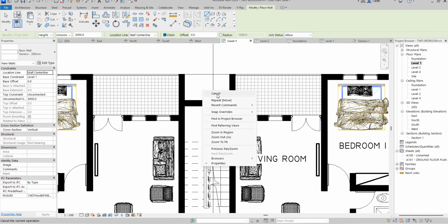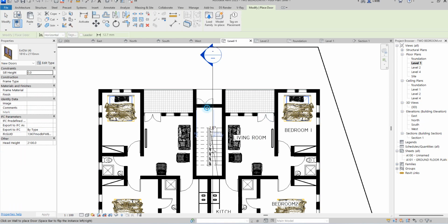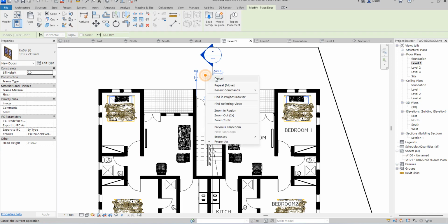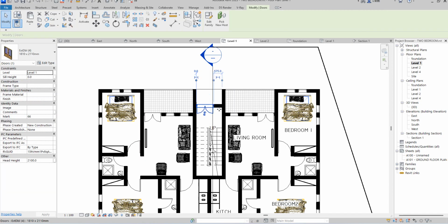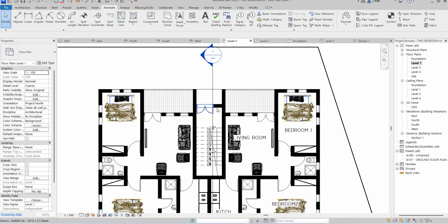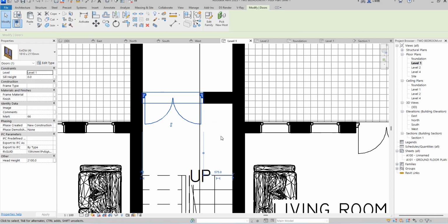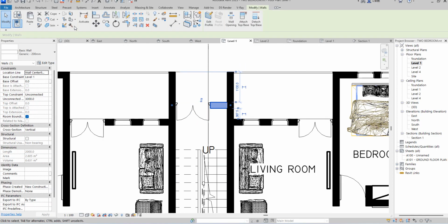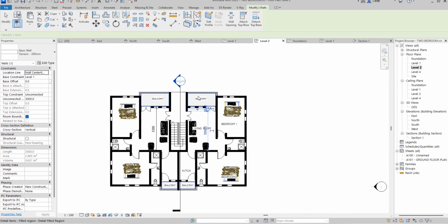What this will implement is that we're going to have a door. The door is going to be somewhere at this side, so that you'll be able to come from here and climb. This particular door is going to go up. So select that door and wall, say copy to clipboard, then go to the upper floor and say paste, paste to current view.